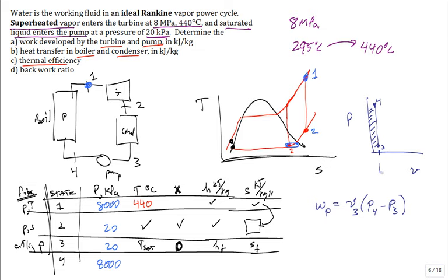All right. Once I know the work of the pump, well, H4 is equal to H3 plus the work of the pump. You agree? So we can just put in H4. We know this S is the same, but we used it because this applies only if S is constant. Okay. And it is an approximation because V truly isn't exactly the same. That's a little bit of an approximation. But we like approximations that work very well, and that works very well.